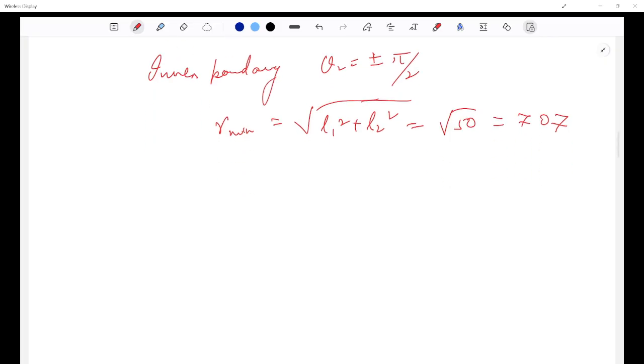Okay, so if I have a full stretch, it is at 0 degree and I can go to the outer workspace, but for inner workspace I cannot completely fold it, because once I start folding it, and my relative angle with respect to what is fully stretched is pi by 2, then my R min would shrink to this.